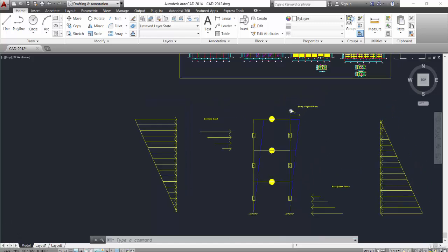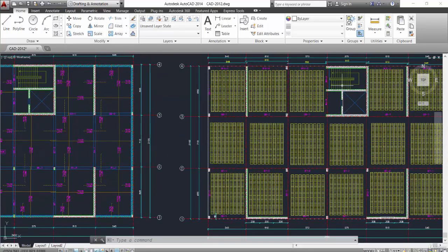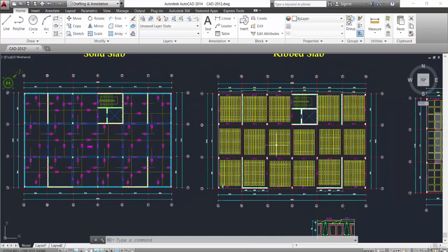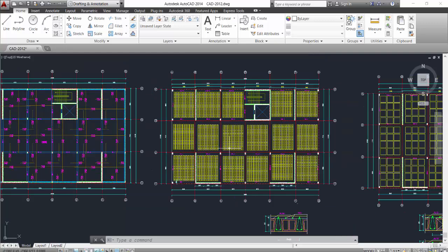Shear wall system consists of using reinforced concrete walls in the building to resist this lateral load. There are many other systems we will define later in this lecture. In our project we use the shear wall system, as we show.